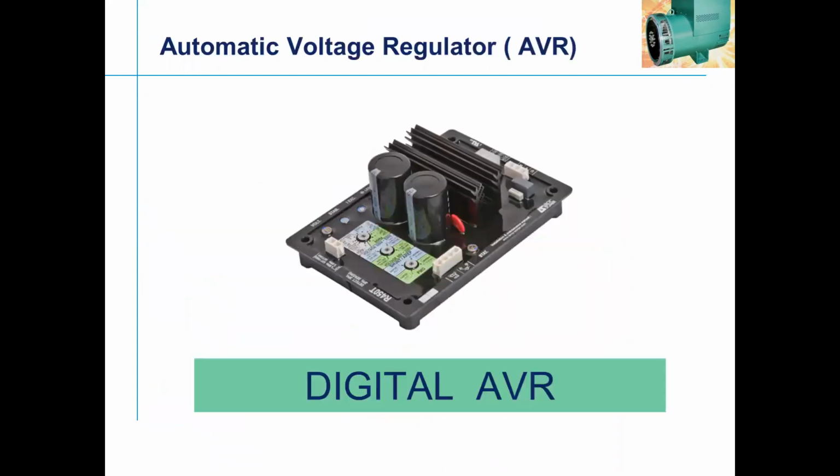Coming to our heart, we have done with the shunt, PMG and RF. Heart has given some, always we have given some feedback. And of course the brain, AVR, our digital AVR. Earlier, pre-90s, there were conventional analog AVRs. Before that, it was brush type generators. Thanks to the digital technology, we move on. And I hope last 5 to 6 years in this field, it is moving on in a big way on